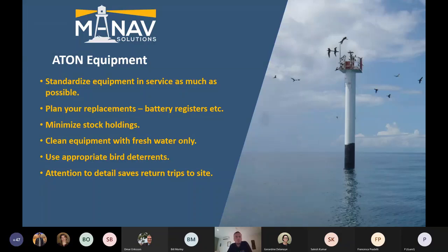And it's important for a maintenance technician to understand that when he is maintaining a piece of equipment, double check everything, make sure your battery cables are tight, make sure bolts are not loose, make sure that you've checked inside the lamp, because quite often just missing one simple detail may lead to a failure, which may lead to a very high cost of returning to the site to fix it.